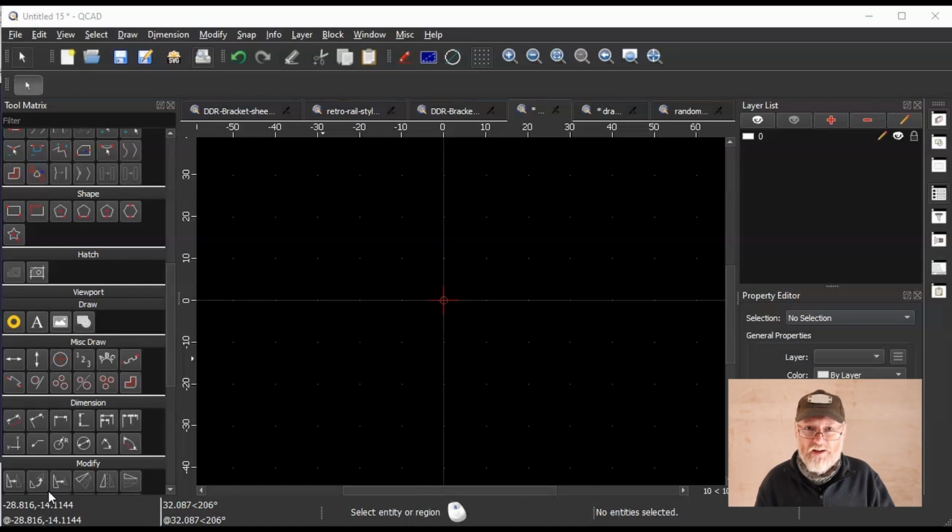Easy mistake to make is you just leave it to whatever the default is when you set up the package, and before you know it, your files are in different dimensions. So from the get-go, set up the parameters, say whichever measurements, so that every time you open the package, it goes to that default. And trust me, this can help later on if you download files or someone sends you something they want cut and they've used a different setting. In theory, your package should pop up with some kind of warning to say there is some kind of difference there.